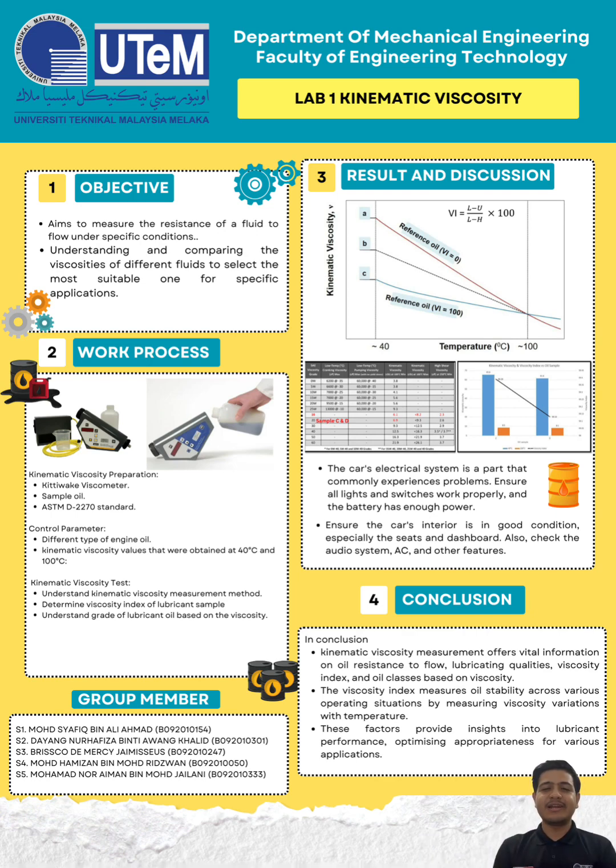Hi, Assalamualaikum. My name is Muhammad Aiman bin Muhammad Jailani, and my metric number is B09201033. I will continue this presentation with my part, which is result and discussion. Based on the experiment we performed, to determine each oil sample's potential SAE, or Society of Automotive Engineers, viscosity grade, the kinematic viscosity at 100 Celsius of the sample was compared to the SAE J300 viscosity grade for the engine.